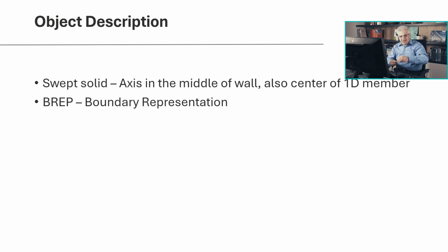And then there's a start point, end point, coordinate system, rotation of the coordinate system, and the description of the column: that we have the column from this point on this line to the end point on another line, with the coordinate system and with a cross section. So you get a full description which can be directly used in SCIAEngineer to create a column.